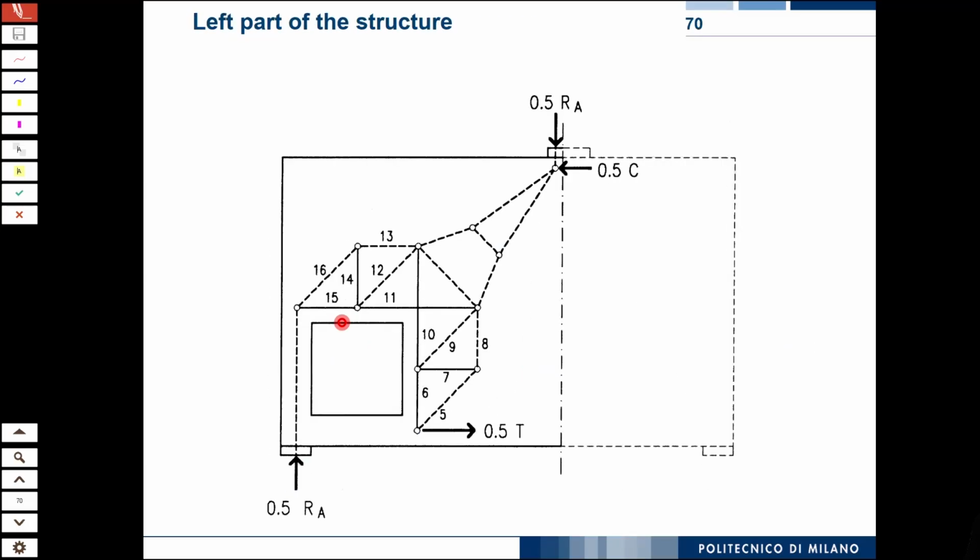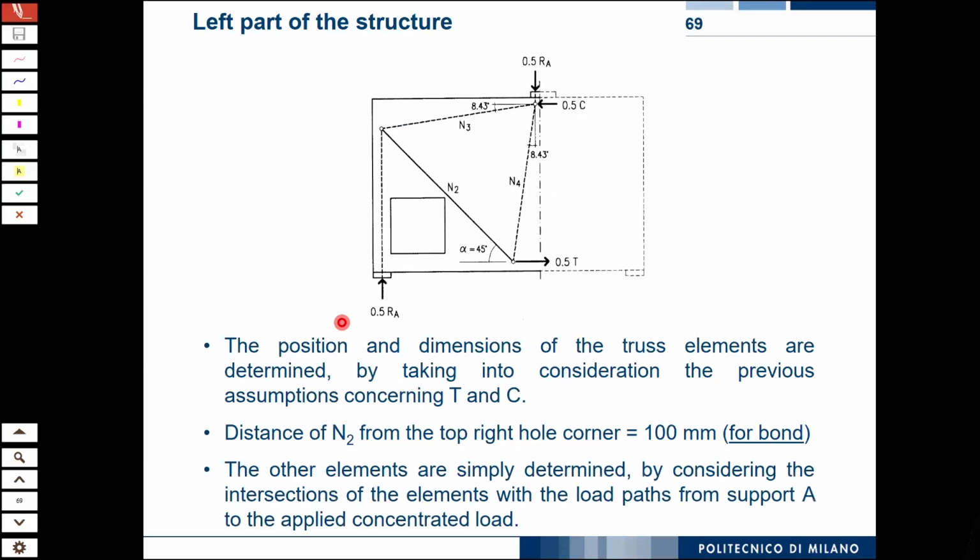Yeah, and the previous one does not have edge reinforcement. Yeah, that's it. This covers the reinforcement here. That is another reason, because we know that from the corners you have cracks going up more or less diagonally, and this is what this does.